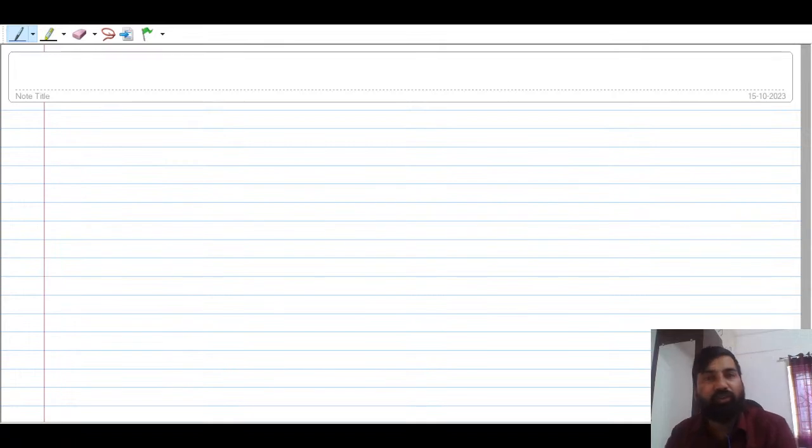I have told you why we go for the Fourier transform. We go for the Fourier transform to know the frequency content of the signal. And we always try to keep the bandwidth of any signal pretty low, and the channel bandwidth should be very high. So the basic resources are power and bandwidth. We talk about the Fourier transform to know the frequency content of the signal so that you can decide the bandwidth of the channel. That is very important.